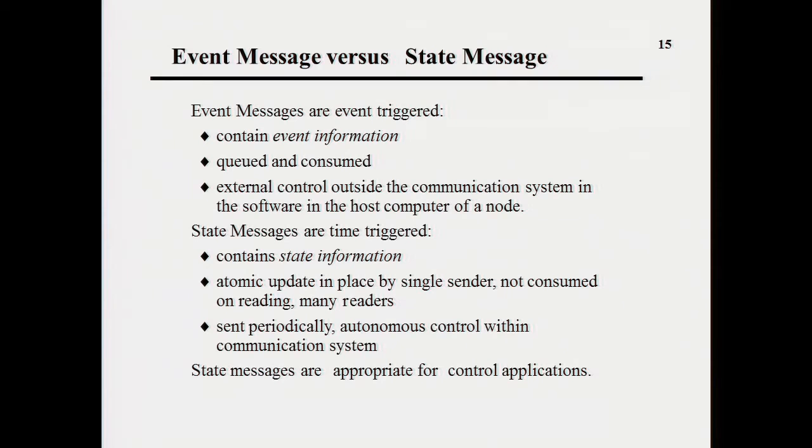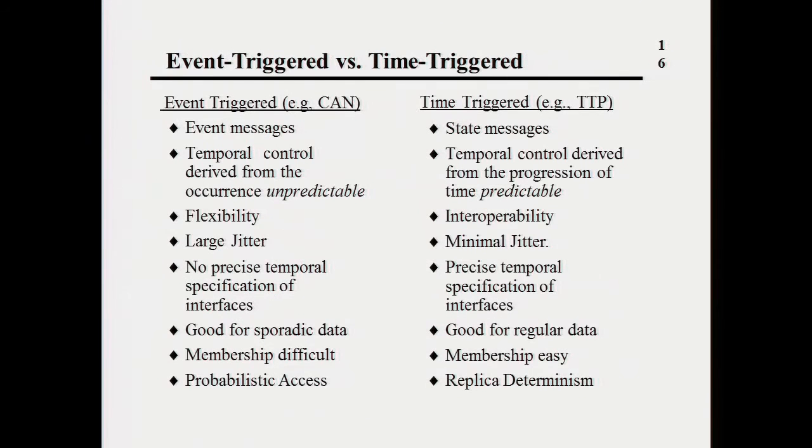And that's one piece of the problem. The state message, as we said before, is time triggered. So whatever I read in the data, that is my message, right? So in the output buffer, that's what it is. And so I don't have to worry about overwriting. I don't have to worry about queues. A two-slot buffer is plenty good enough. It's all I need. So no queues, no nothing. Of course, the problem with the state messages is that the state may not be the real state of the system. And so that's the reason why we have to keep the boundaries of the slots close to each other.